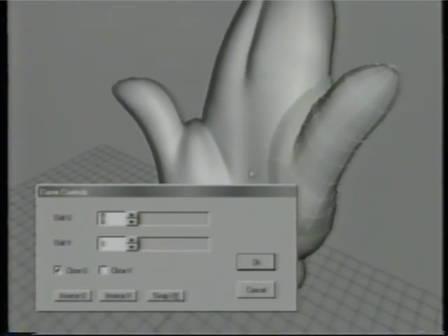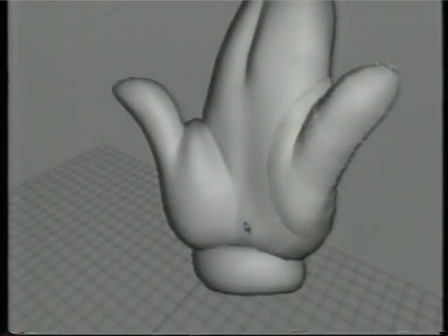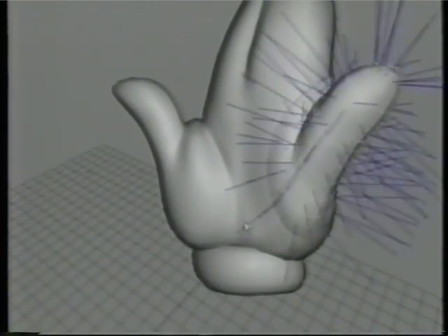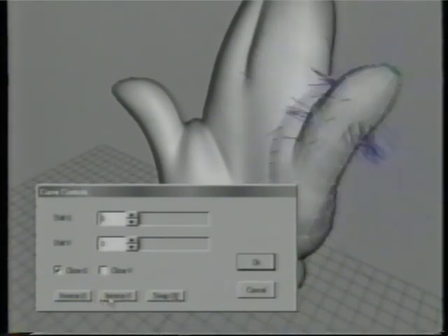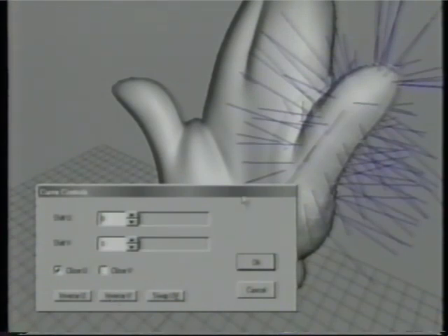Now you'll see it's inversed. Change color. The best way to do it is to turn on normals before you enter that box. And you can see you can swap. Then you'll need to inverse the U, not the V. That way you have the green, or the U, at the bottom, and the normals facing outward, and the red along the seam.